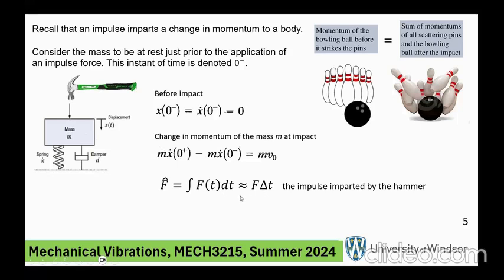So this is the impulse of that force over a very short time, of some magnitude. This is approximated with F times delta T. Remember, this is all integrated from minus infinity to plus infinity. I know that. Impulse is defined as the integral from minus infinity to infinity of F of t dt. But notice that this force is alive over a very short interval, delta T. So this thing is equal to that thing, and this is coming from the impulse momentum equation.